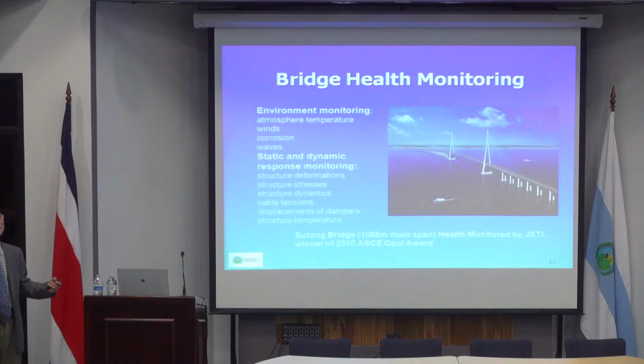It has many redundancies. When you have many redundancies, they have different modes of vibration, different shapes of vibrations. But basically, the lowest frequency vibration we call the base vibration, and then there's the second, third, and so on. So the total vibration is a combination of that. Now the computer can actually isolate vibration. Actually, it's not difficult. It's just mathematically getting the first frequency, second frequency, third frequency vibrations.